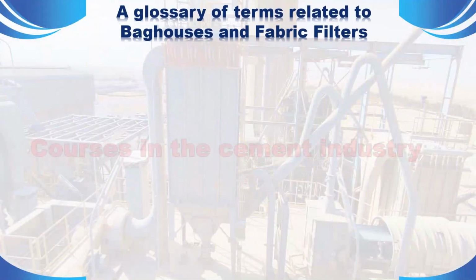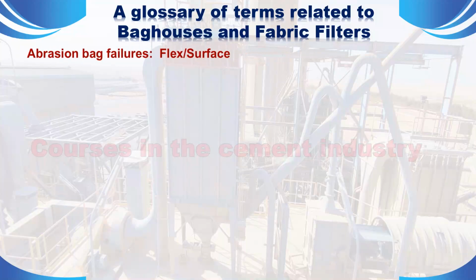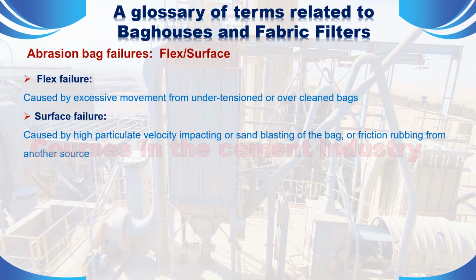A glossary of terms related to baghouses and fabric filters. Abrasion bag failures, flex and surface. 1. Flex failure. Caused by excessive movement, from under-tensioned, or over-cleaned bags. 2. Surface failure. Caused by high particulate velocity impacting, or sandblasting of the bag, or friction rubbing from another source.